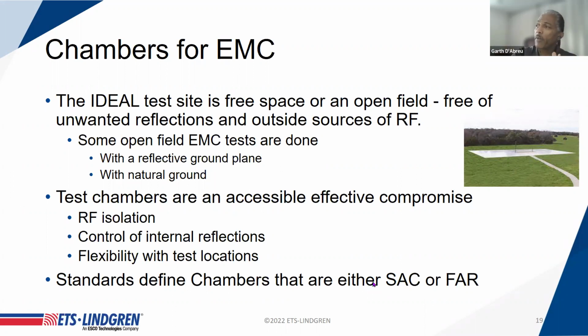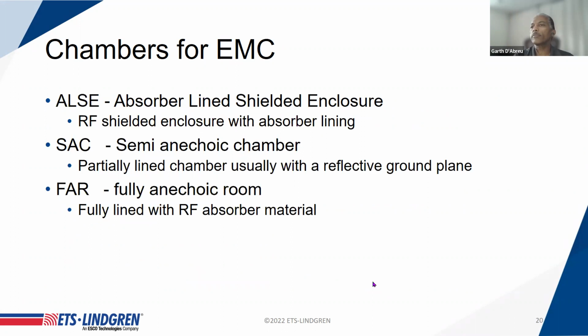The challenge with this environment, obviously, is that in a lot of cases it's exposed to the weather, and it requires a bit of real estate which is free from external RF influences. There's a lot of RF in the environment, so finding somewhere to put a big greenfield OATS that's not subject to cell towers and televisions and radio and everything else is very, very challenging. So what most people end up with is some form of enclosed facility which meets the minimum requirements of the particular standards that they'd be testing towards.